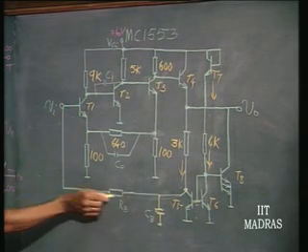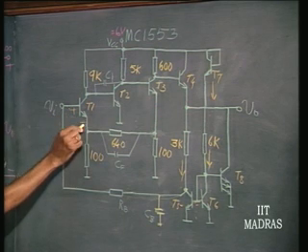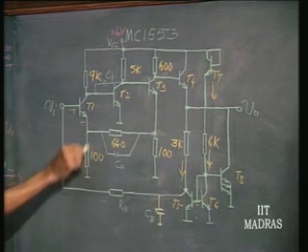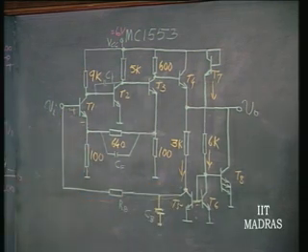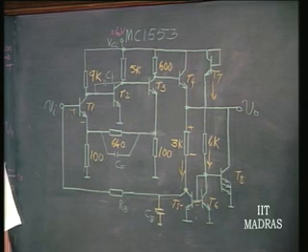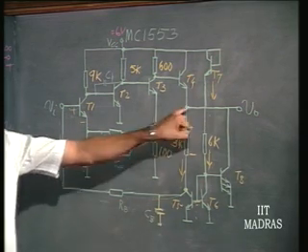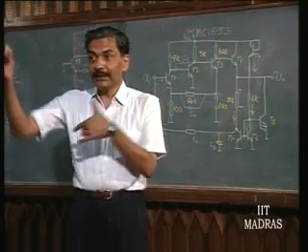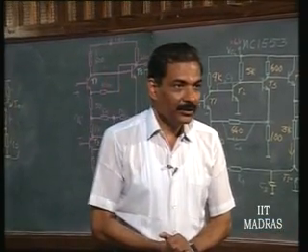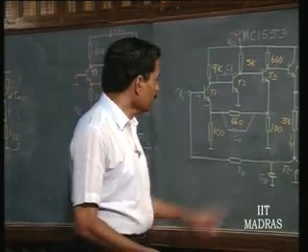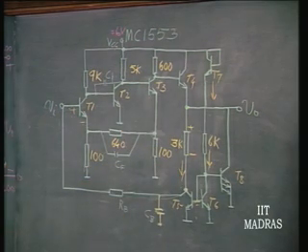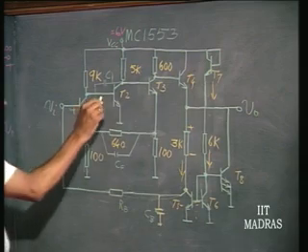You have to come back here, there is no potential drop here, there is V gamma here, there is very little drop across 100 ohms, because this current is going to be very small, that is what drop across this is very small, we say. So, this is roughly going to be 0.6. Okay. So, we know that this is 0.6 and there is going to be a drop of 3K into how much? 0.8, which is 2.4, and therefore, output voltage quiescent value is 3 volts, which is the center of 0 and 6 volts. So, that you can get fairly good output swing for this particular structure. So, you can see that this output quiescent is very nearly at 3 volts by this kind of arrangement here, okay. And you can evaluate the other DC voltages and DC currents.